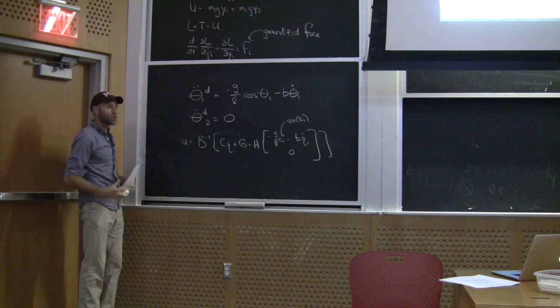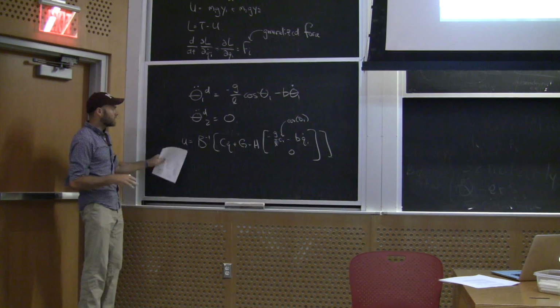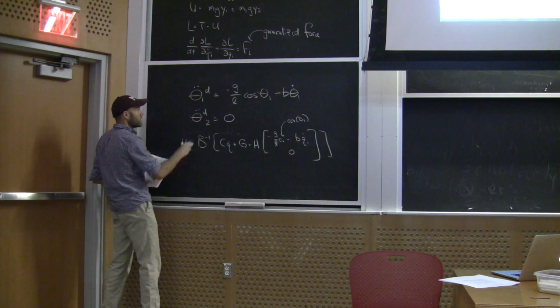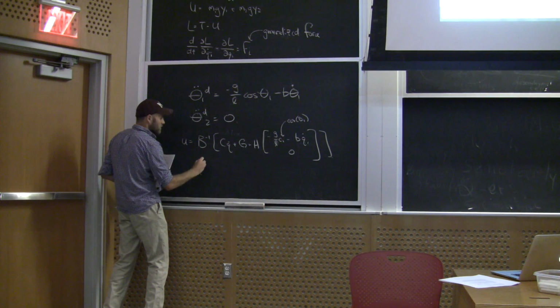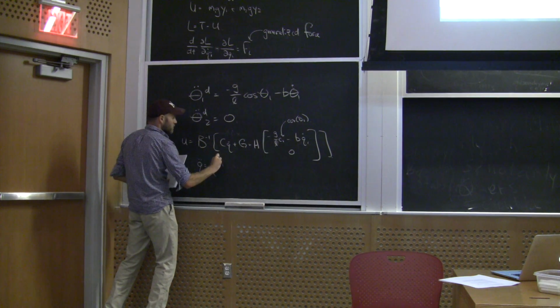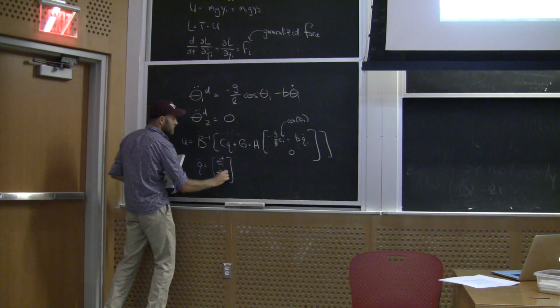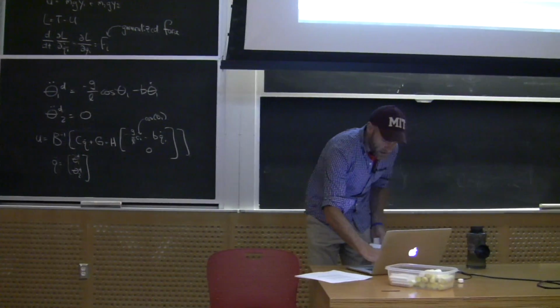If I write down some controller like that, type that into MATLAB, which I've done, and simulate that forward, this is the feedback linearizing controller. It's going to make the resulting dynamics, q double dot, equal this: theta 1 double dot desired, theta 2 double dot desired. Okay, and I can simulate that.